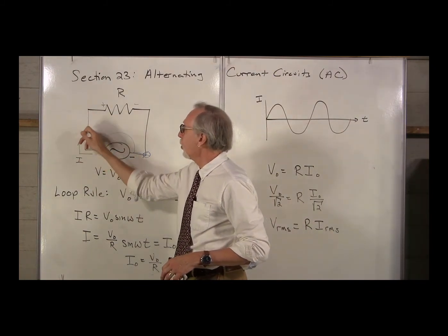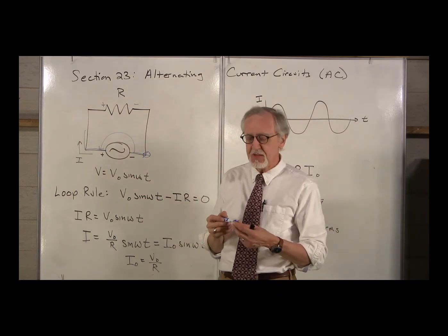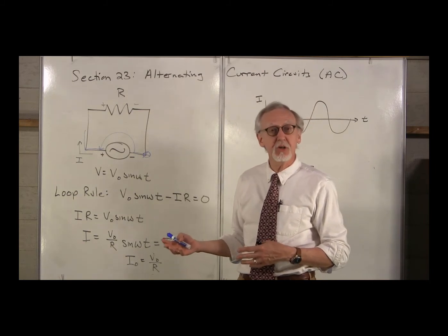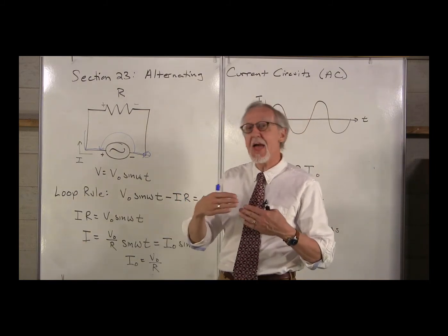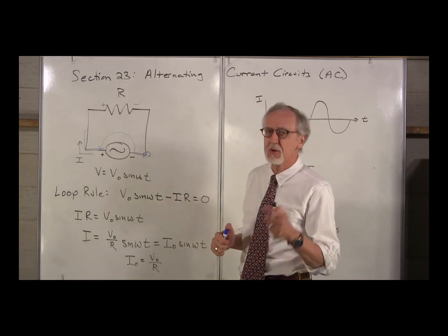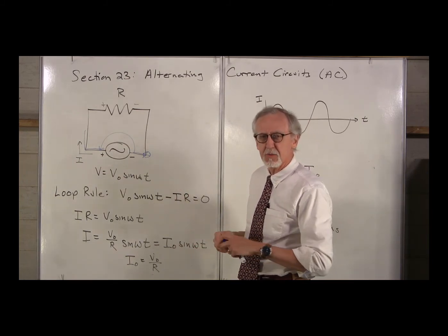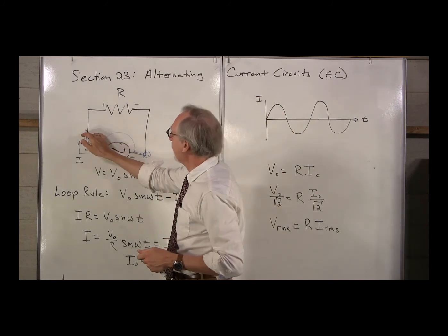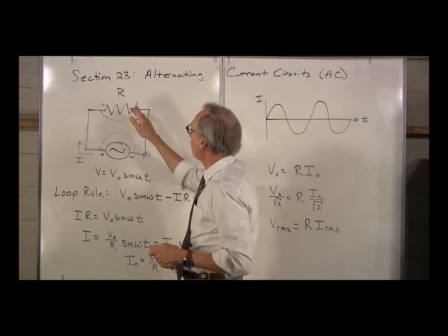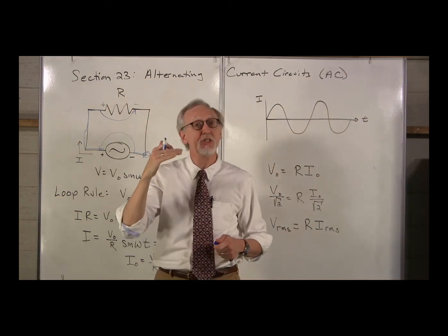Continue along. We are going to assume, like we usually do, that the resistance of the wires is negligible compared to anything else in the circuit, so there's no voltage change as we move along a wire. It's a bit of an approximation, but it's a pretty good one if we remember the resistances of wires that we found before. We continue up here, jump across the resistor. We're going from the high side to the low side, so that's going to be a voltage decrease.